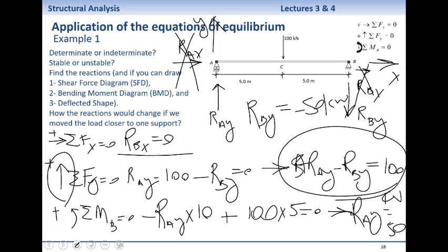Therefore, when you start and you draw the free body diagram, don't worry about the directions. Don't try to guess. But identify the correct reactions. In this case, we know that at A, there is no horizontal reaction. That's important. But the directions are not, because equilibrium will give you the right direction. Okay, fantastic. That's great. Any questions? Anything that you need more explanation there?